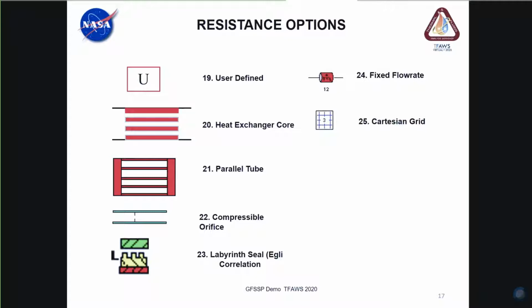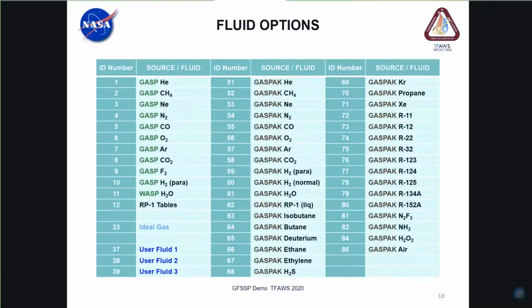That would allow you to do a very simplified 2D model, but at this time there's no turbulence modeling in it, so it's really just for simple laminar flow problems. It's really more of academic interest right now. And there's a user-defined branch as well, where you can model the pressure drop versus flow rate of code and program the equations for it yourself in Fortran.